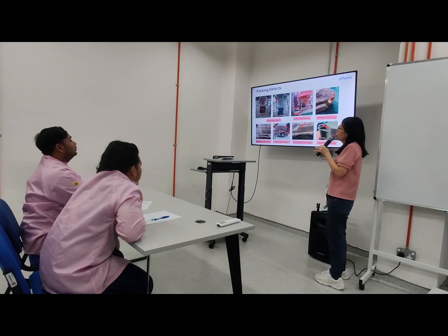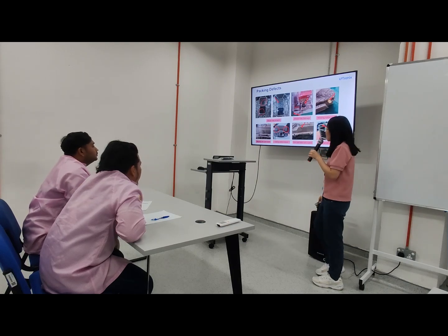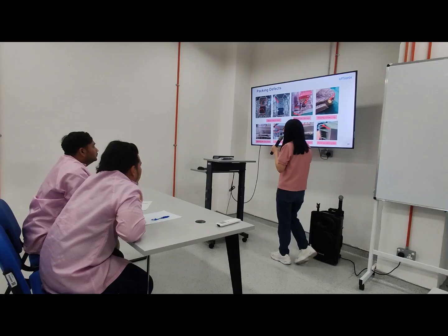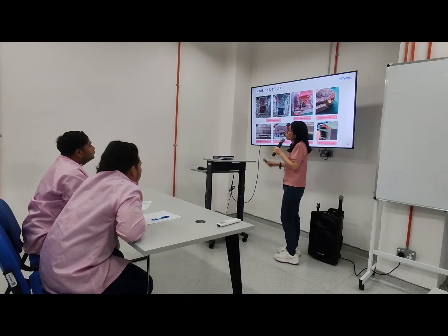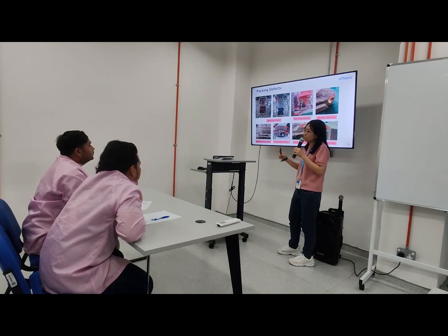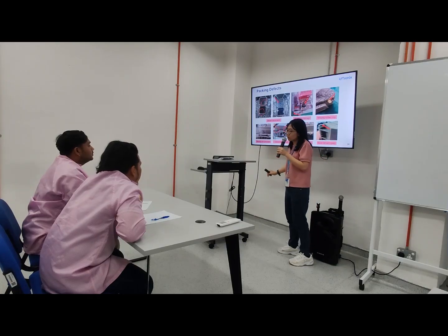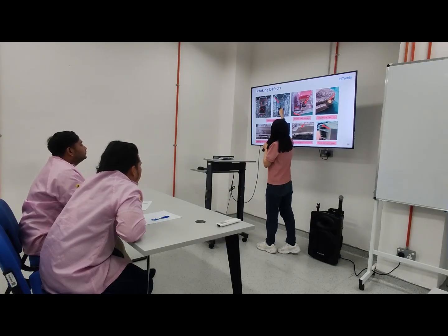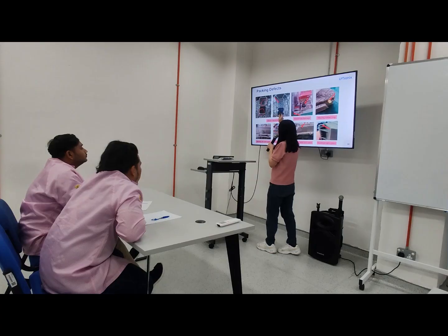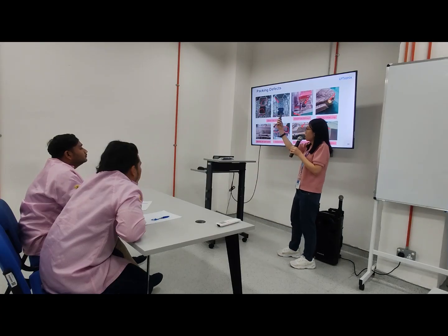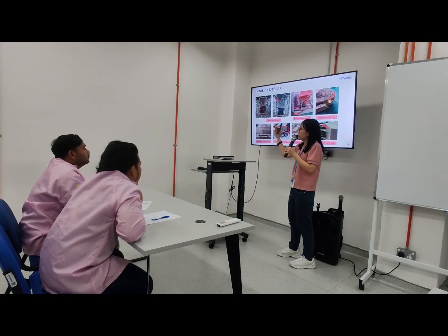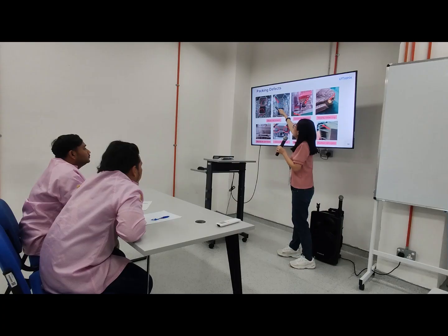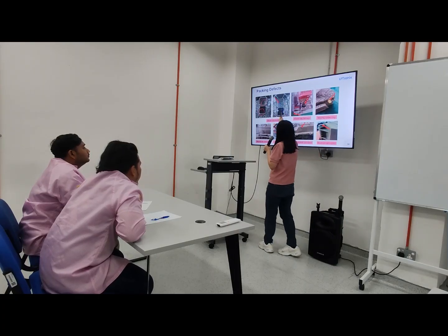Next, we'll go into packing defects. For this kind of packing that we use, the blister tray, the most common defect is the scratches. Especially this area, because this product will be hanging on the rack. Then first we will see this area. So this area, ensure no scratch at all.